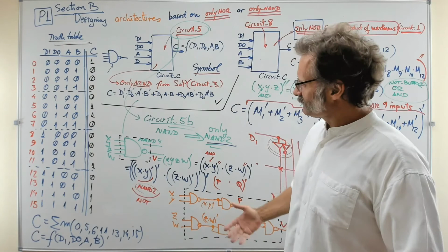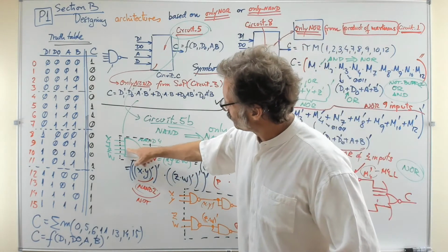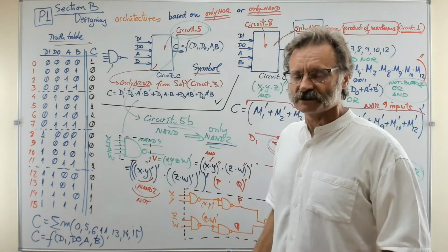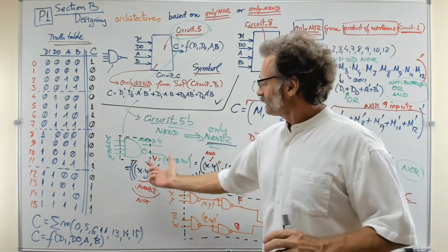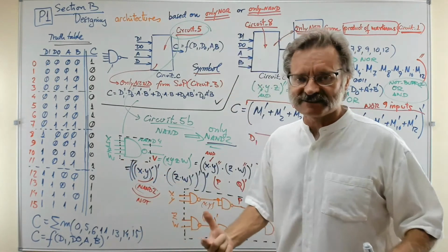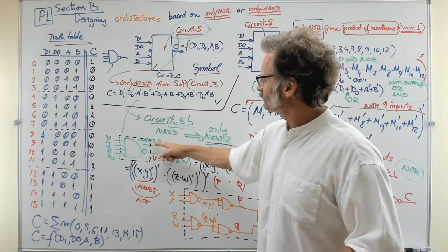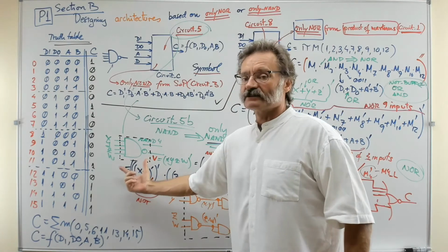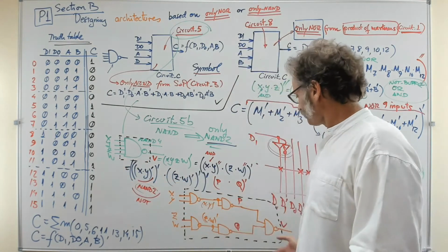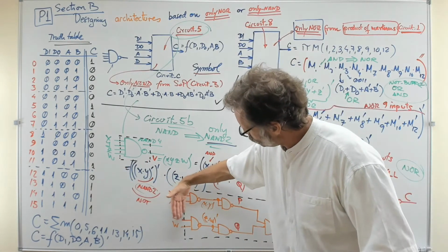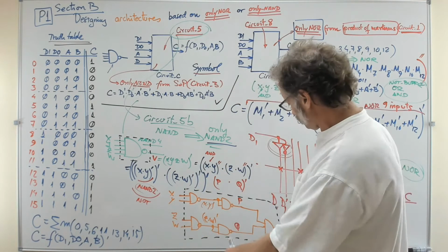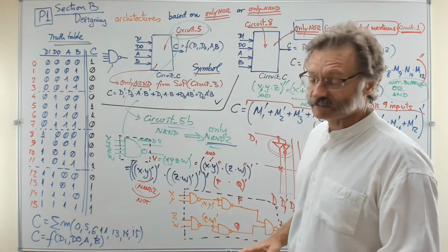But you can imagine now that if you can synthesize a gate like this, a NAND of 4 inputs, as a single circuit, that one is going to be faster. Solving the NAND 4 truth table is going to be 3 times faster than this one here, because here the signal has to go from one level of gates to the next and to the next to get the same table, alright?